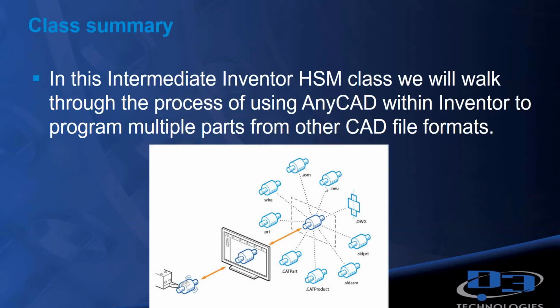So here you can see an image of DWG, SolidWorks parts, CATIA. It doesn't have it on here, but STL, STEP files. It can not translate, but rather reference all those types of files into Inventor so that we're not having to remove the link between the two. So where you update it in one system, it also updates inside Inventor. So we'll see how that looks here in just a little bit.